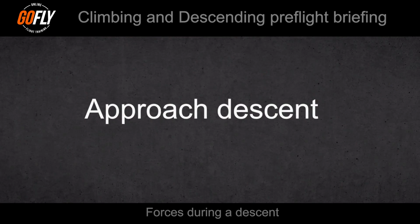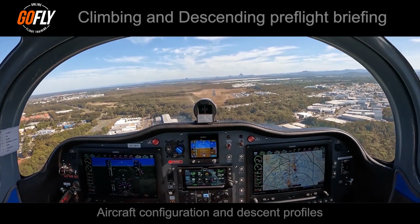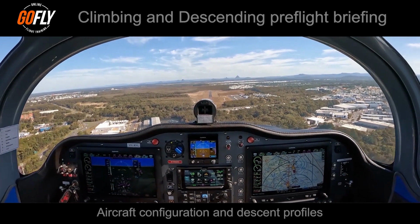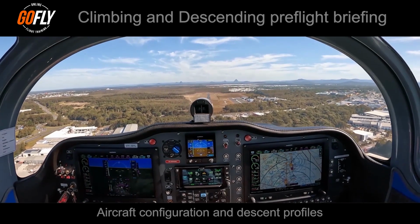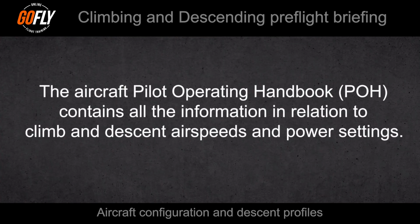An approach descent in the descent configuration during an approach to land would normally involve flaps, and if the aircraft has retractable undercarriage, the undercarriage would be extended. For a glide descent, the Pilot Operating Handbook, also known as a POH, will advise what the best glide speed is for that aircraft type.